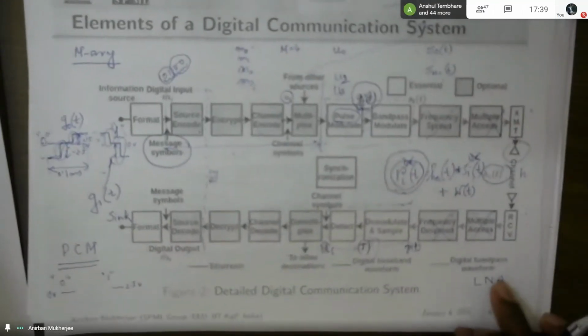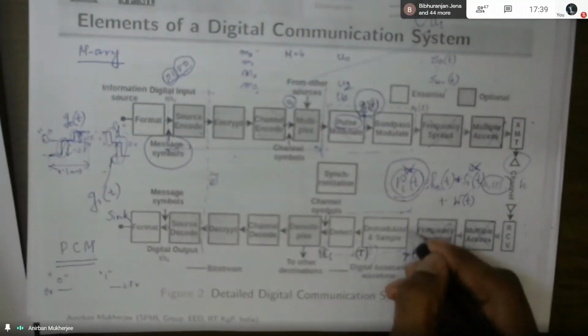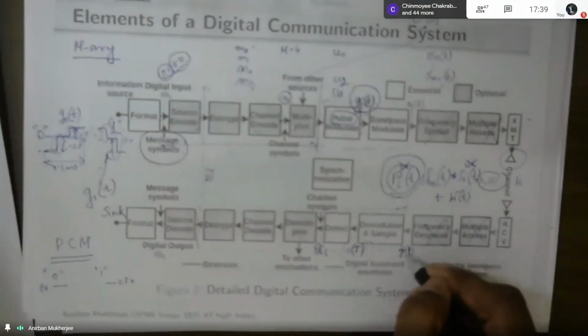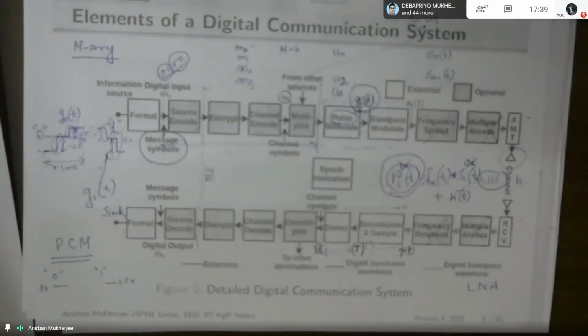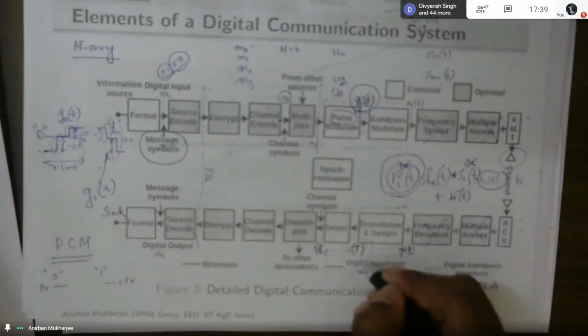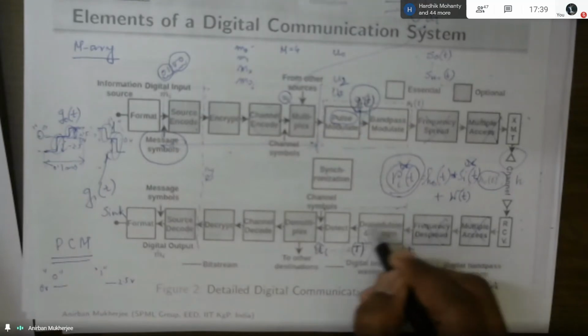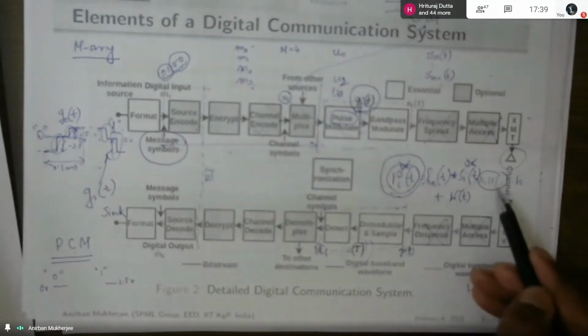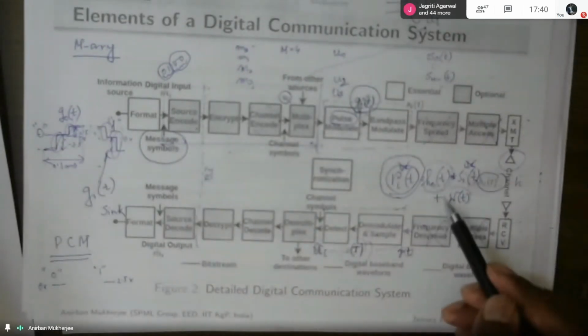Now the demodulator, this one: its input is that r(t), or you can say ri(t), and it restores r(t) to an optimally shaped baseband pulse z(t). Please see, here I have written capital Z(T), that is after sampling, over here. But just after demodulation from this, because r(t) is noise corrupted and also impaired by the channel impulse response. The channel impulse response is not delta.